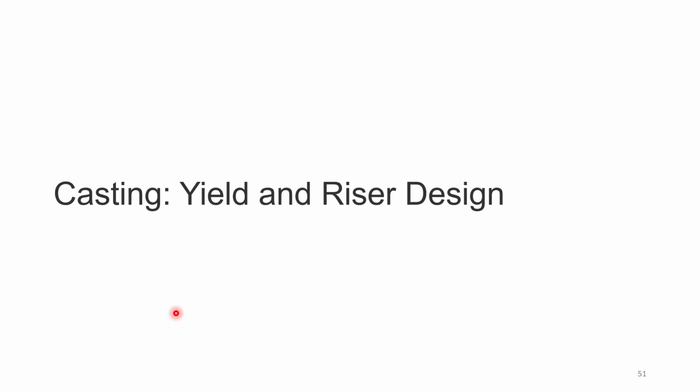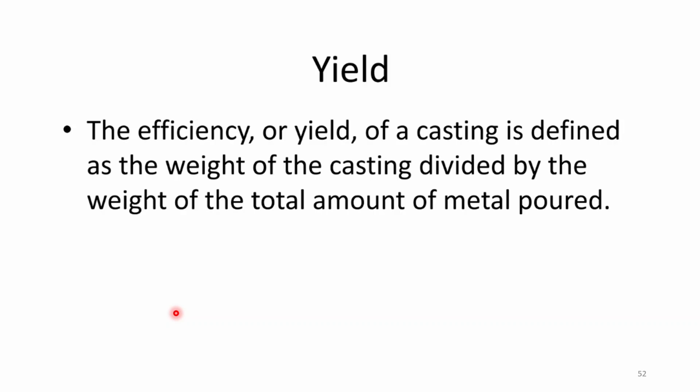Next chapter is casting yield and riser design. First you have casting yield. It is the efficiency or yield of the casting, which is defined as the weight of the final casting, the usable part, divided by the weight of the total amount of metal poured.